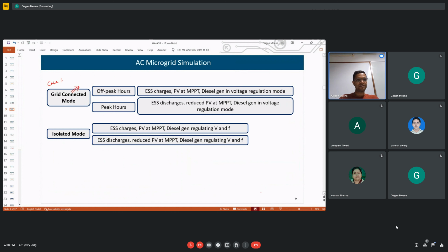And for effective filter design, the overall impedance must be less than the source impedance. So that is why a large size of filter is required, which causes overcompensation. That is their limitation, and that is why active filters are introduced, so that they can adapt, because they are based on converters, as we can see on this slide. In active filter also we can have shunt, series, and third is hybrid, which is UPQC, Unified Power Quality Conditioner.